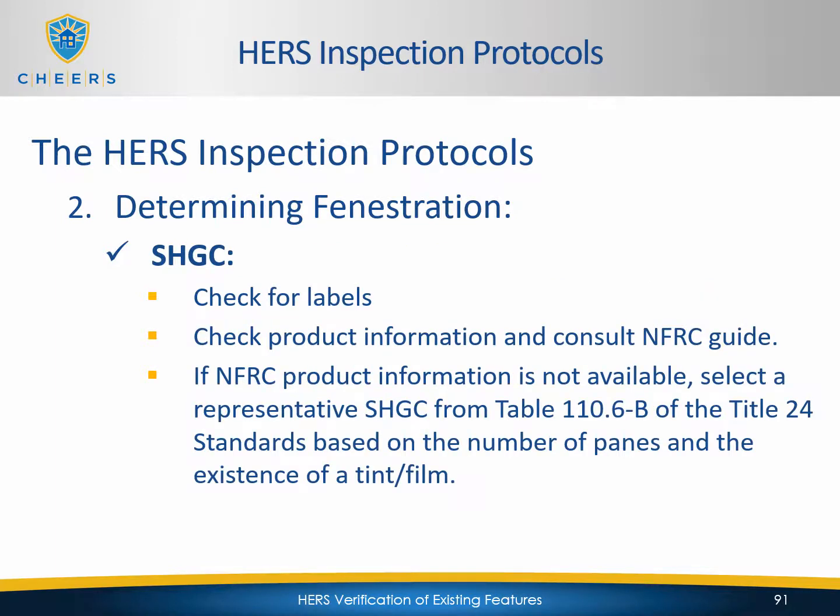Solar heat gain coefficient, so you want to check for labels if available, or you can check the product information and consult the NFRC guide. If the NFRC product information is not available, you want to select a representative solar heat gain coefficient from table 110.6-B of the Title 24 standards based on the number of panes and the existence of a tint or film.